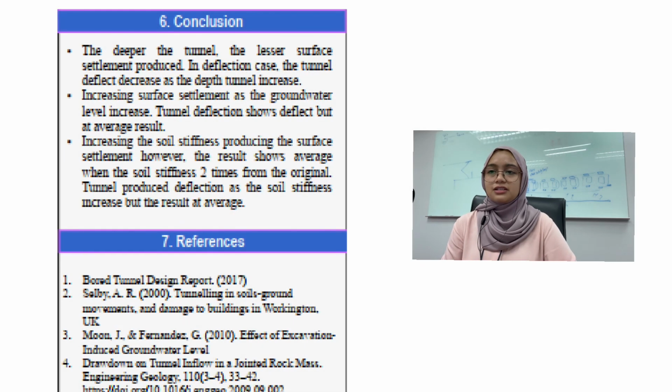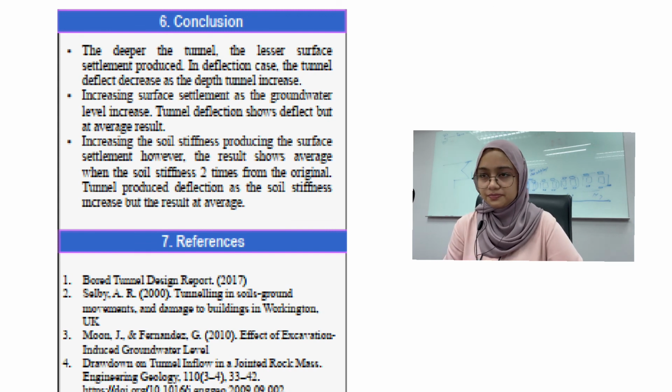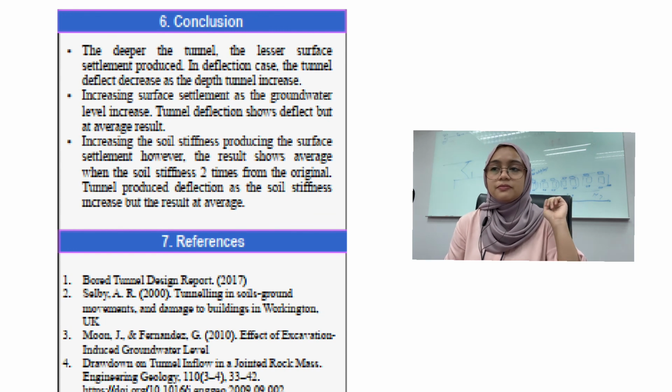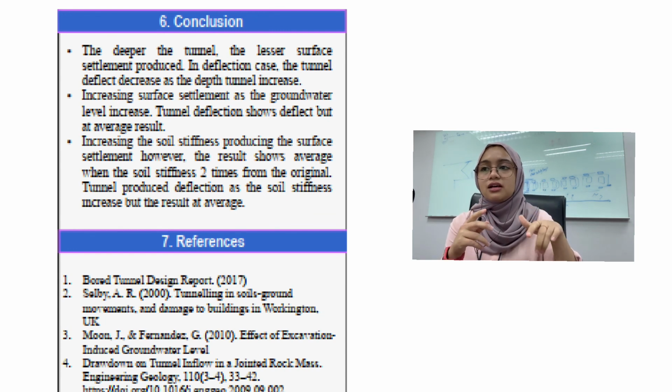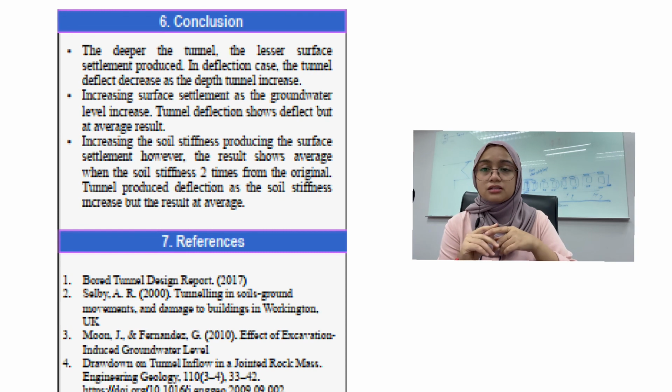For the conclusion, observing the effect of settlement change during tunnel excavation is one of the objectives that have been achieved. From the study, I found that changing the tunnel depth, groundwater level and soil stiffness will affect the surface settlement and tunnel deformation.